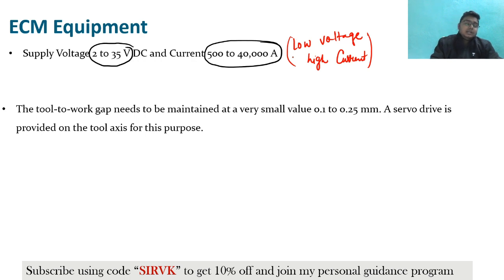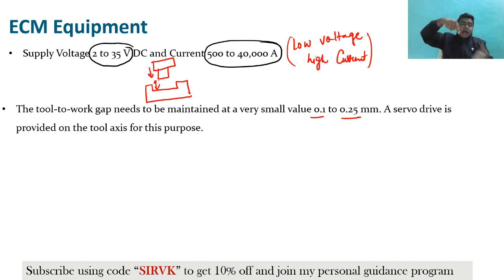Now see here, the tool to work gap, whatever I have told you. This is a tool and this is a workpiece, and there is a gap between them, isn't it? The tool to work gap needs to be maintained at a very small value of 0.1 to 0.25 mm, and a servo drive is provided on the tool axis for this purpose. I have told you there is a servo mechanism associated with the tool, so the tool gets continuous feed, and the optimum distance between the workpiece and the tool is totally controlled by the servo motors. The gap should be 0.1 to 0.25 mm.